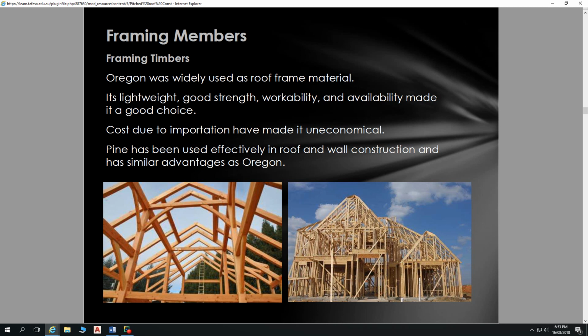Oregon is also very easy to cut. Pine has that softness, it sort of yields under a saw rather than cutting as nicely as Oregon. So Oregon's a lovely timber to build with. We don't grow that in Australia. That's all imported timber, from back in the day when Australia was exporting a whole bunch of stuff to the US, and then ships had to come back with something. They came back with timber.